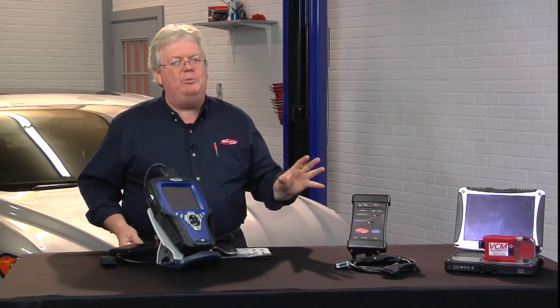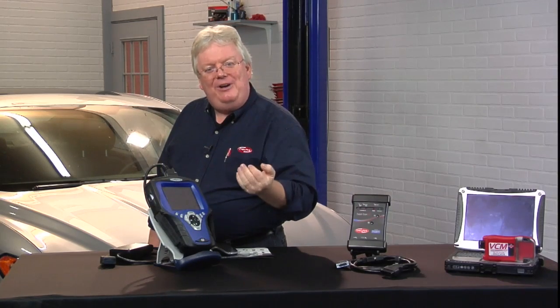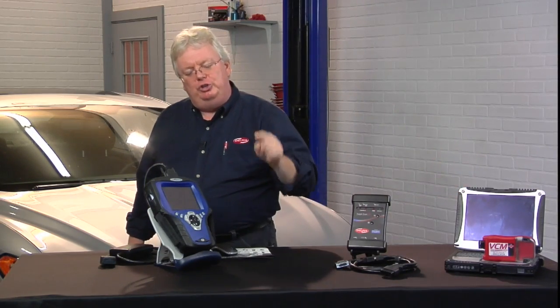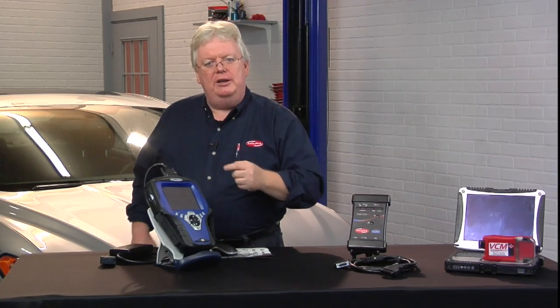We're going to do a little practice with mode 6 on a classic case. If you've ever done mode 6, I know you've done it on a Ford pre-CAN post-OBD II misfire, especially those intermittents where you're really not sure what cylinder is misfiring. You don't have the Ford IDS, which makes that work easy, but you do have an aftermarket scanner with mode 6. So let's get started and do this case study.